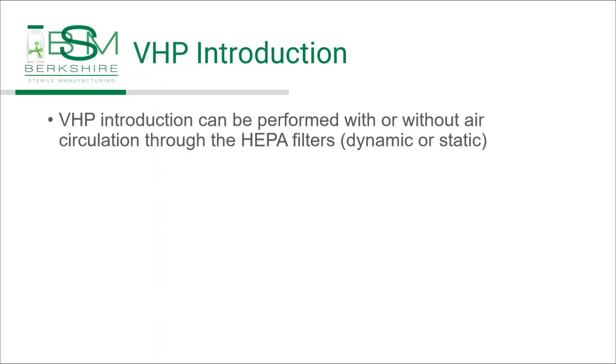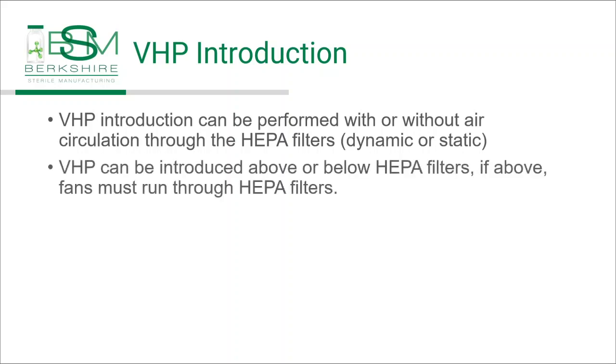VHP introduction can be performed with or without air circulation through HEPA filters, that is dynamic or static. VHP can be introduced above or below HEPA filters. If above, the fans must run through the HEPA filters to circulate the VHP to the area down below the HEPA filters.